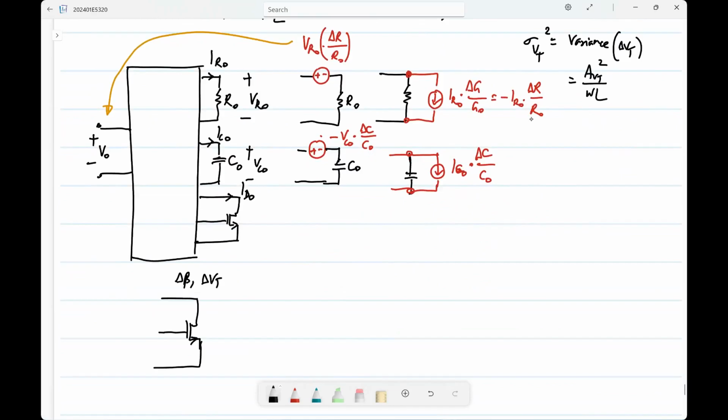Again, obviously, I want to represent the MOS transistor as the nominal MOS transistor plus some additional sources, so that I can do circuit analysis to find the effect. Okay. So how will I represent the effect of delta Vt, for instance? Current source where? What is the most natural way to represent the effect of delta Vt? What do you think it is?